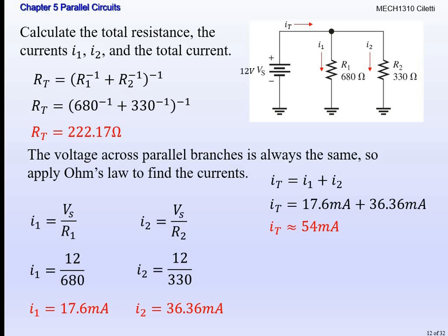So hopefully we're getting down pat. We know how to find the total resistance when we solve a parallel circuit now, that it is nothing like solving for total resistance in a series circuit. Ohm's law still holds true. All right, the relationship between current, voltage, and resistance. And then current, we had to use Ohm's law to do it, but what we learned is Kirchhoff's, however you say it again, right? His current law, the sum of the branch currents have to equal the total current. Make sure you got all this in your notes, all right? It'll come in handy when you show up to take the lecture quiz.